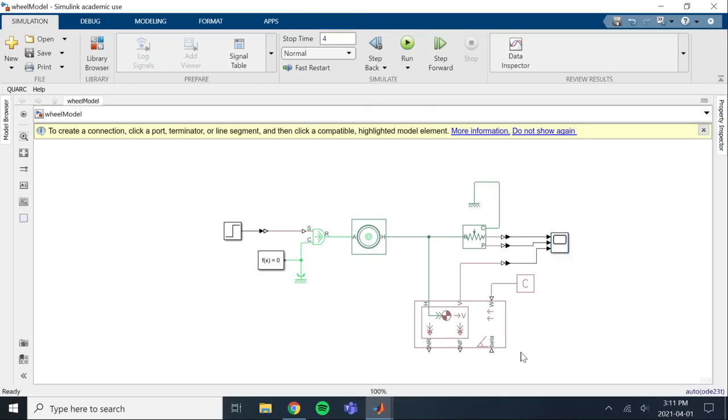Okay, so the next thing we're going to do is this NF and NR output signals, they're not really important to us. That's if you were building a car and you had specified axles. This is basically adding normal forces to each axle. So depending on how the car is starting and stopping, it just applies different normal forces to the back and the front axle. We're not going to do that for our rover because we don't actually have axles. We have suspensions that have 3 different legs on them. And then 2 sets of suspensions, so 6 legs total, each with 2 wheels on them. So it's not going to work the same for us, especially using a rocker bogie setup. It's not going to be the same as a regular vehicle.